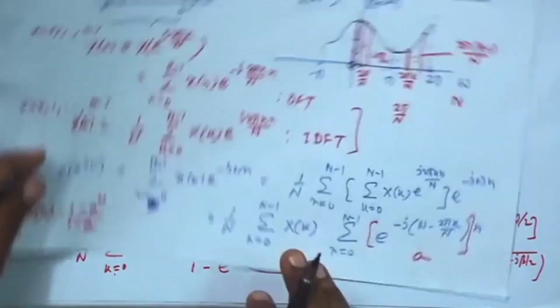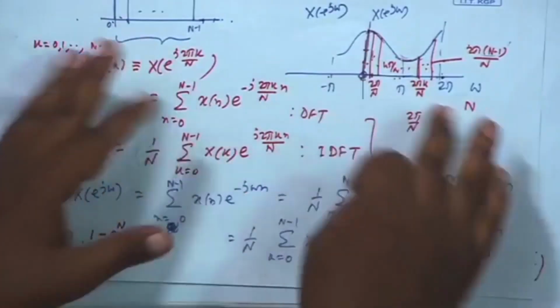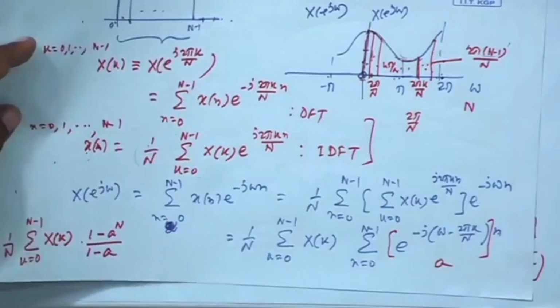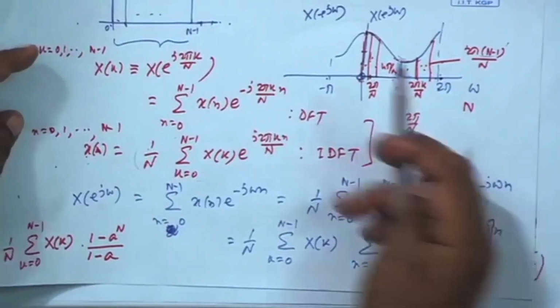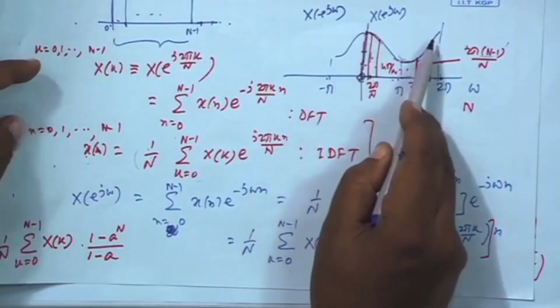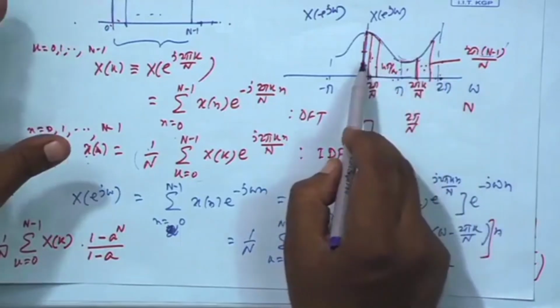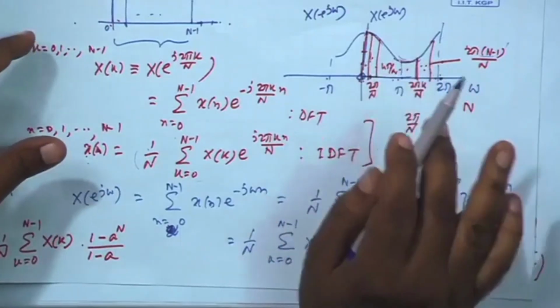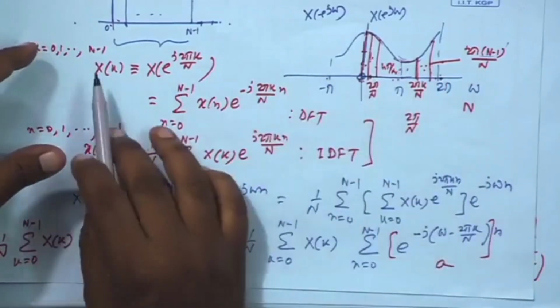Okay. Anyway, this shows that the DTFT envelope can itself be obtained from its own samples, if the sequence is finite length of N points and I take N number of samples. So, no need to store the entire DTFT envelope, just the most important are the N samples, using them I can do anything, I can get back original x n, I can get back original DTFT. This is property number 1.